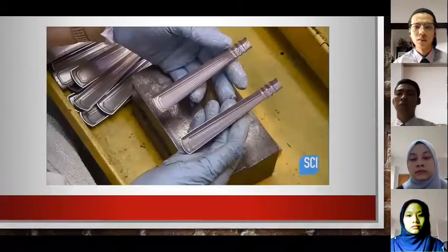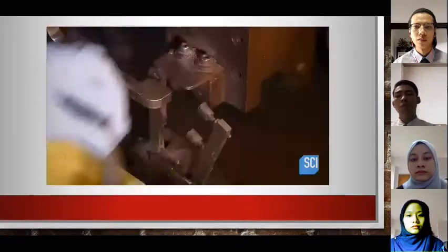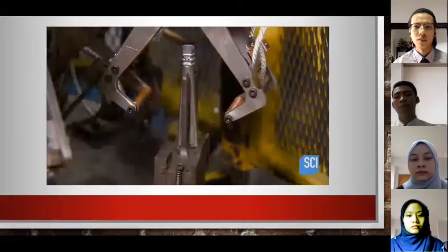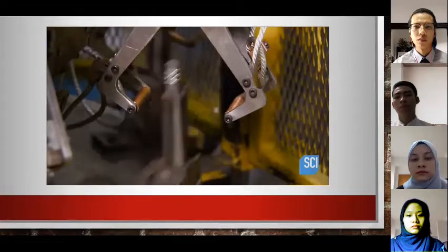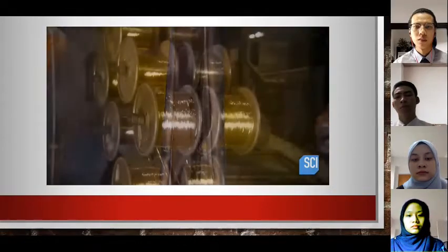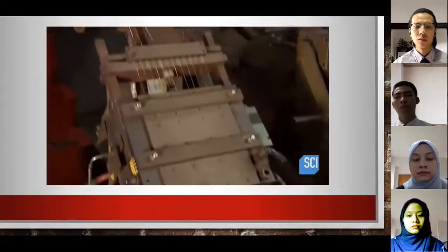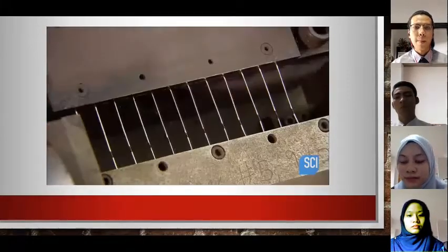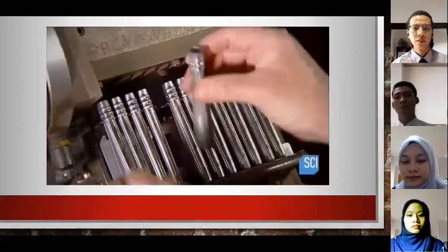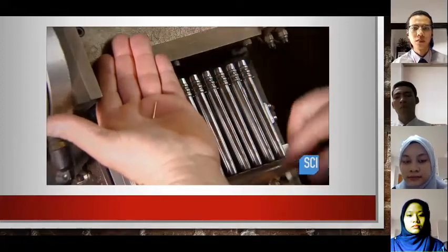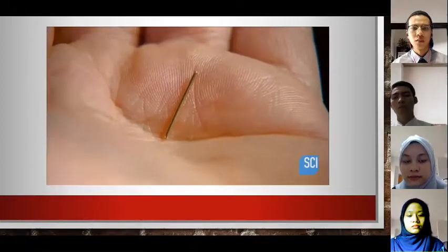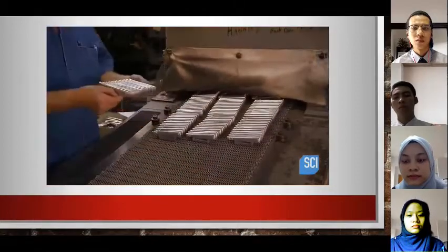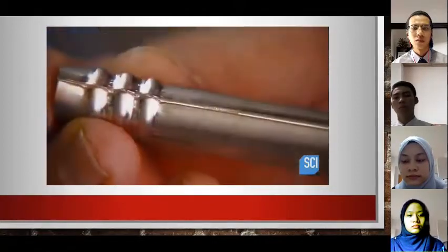Each forged knife handle piece starts out as half a handle. A spot welding machine tacks the two halves together, forming a complete handle. To fuse the halves completely, this machine cuts a piece of copper-based wire and drops it inside the hollow handle. A furnace melts the wire so that it flows into the crevice between the two halves, soldering the seam thoroughly.